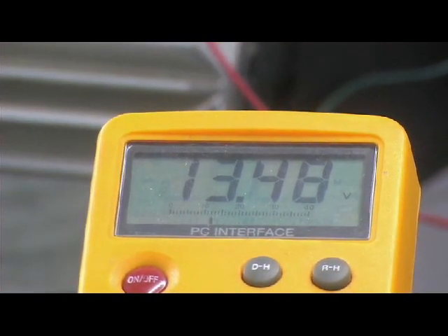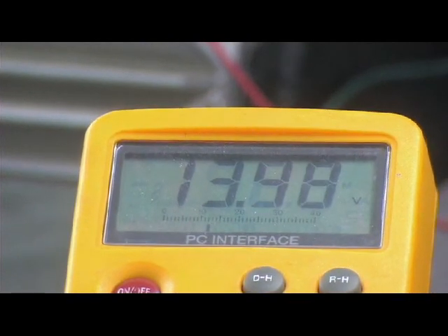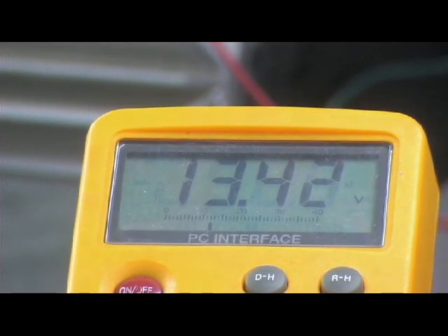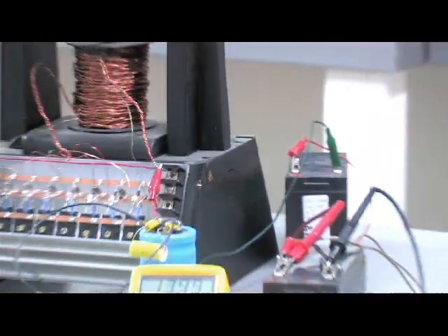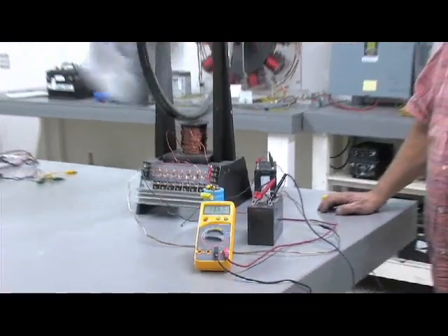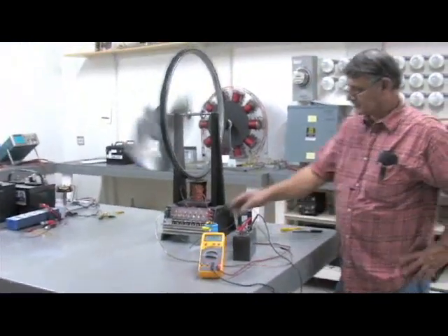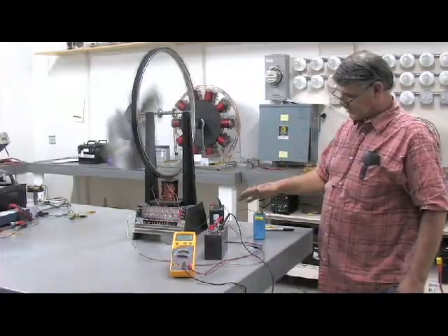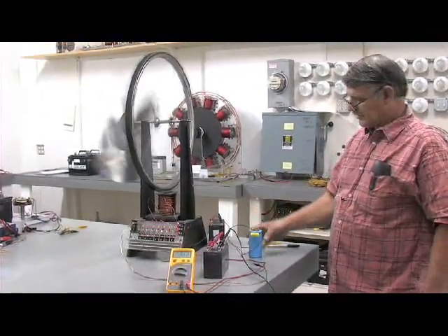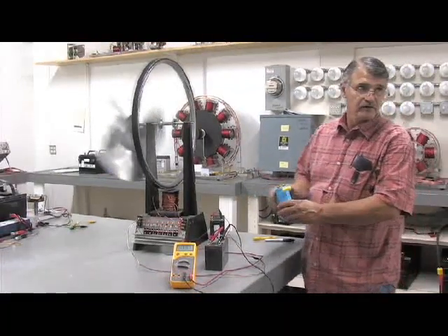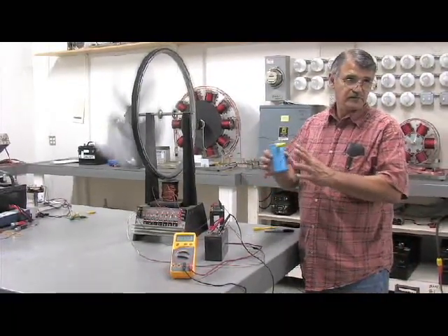You only had that on the capacitor for what, a few seconds? Yeah, less than that. We want to discharge this capacitor. And then the other thing is don't leave the capacitors open because they sometimes build another charge. Do you notice that they build their charge when they're near to these machines? Oh, no. Just after we use them, sometimes they build up another charge, and we think that's the residual left over in the plates as they expand back.